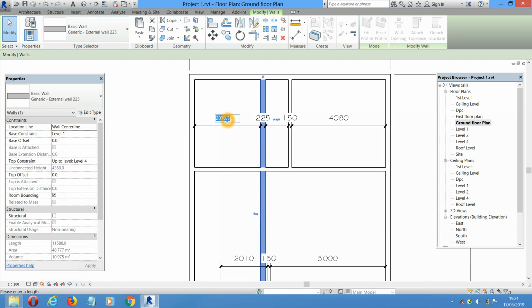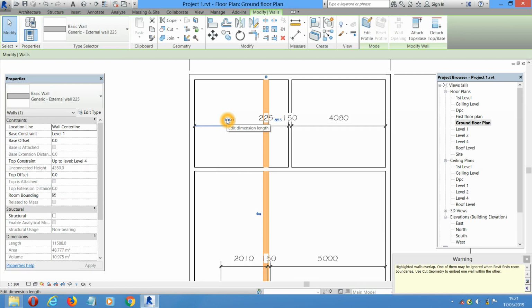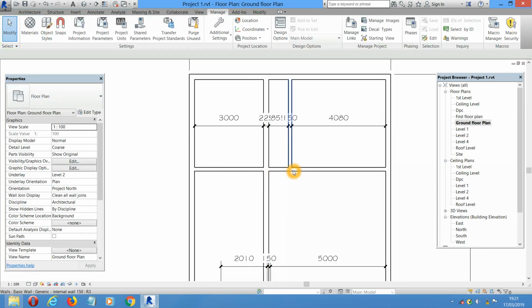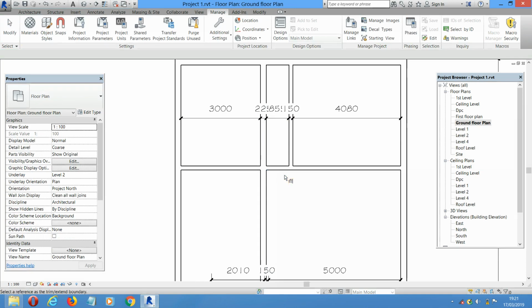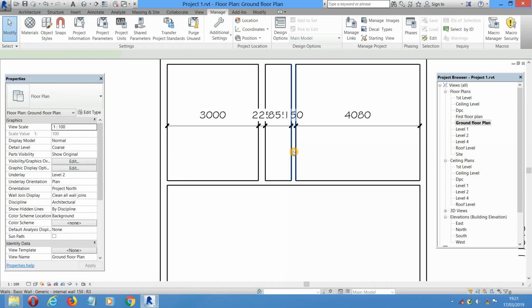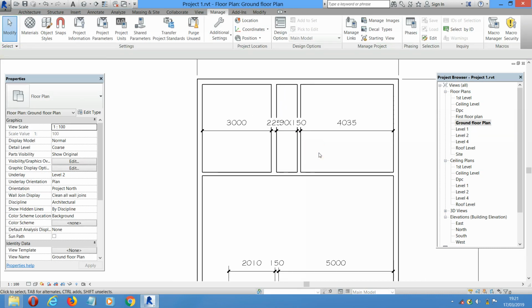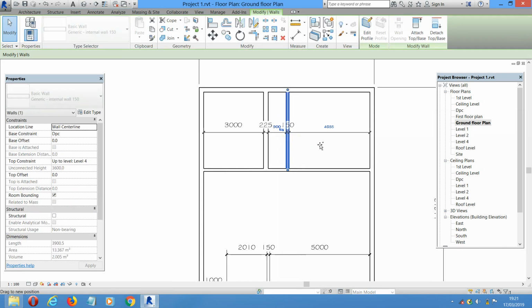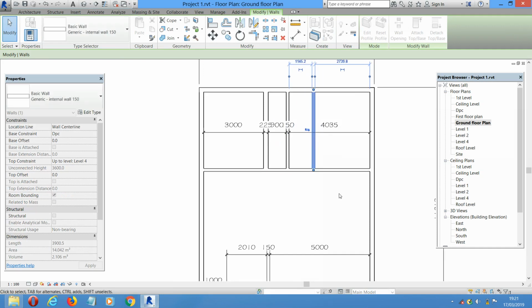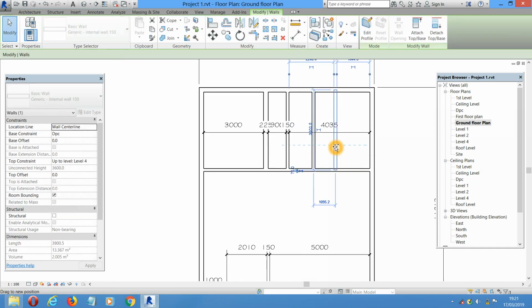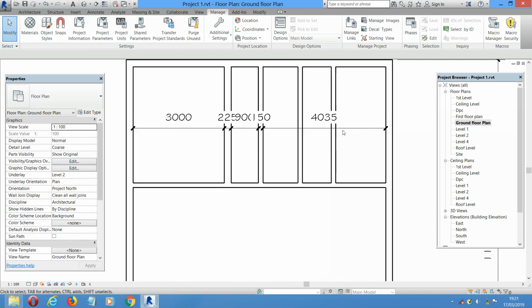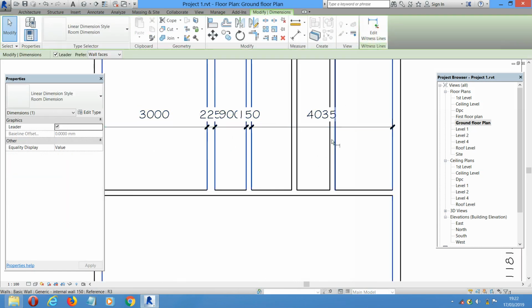So this guest room is going to be 3 meters. Hit OK. Then I'm going to trim that wall. EX is my shortcut for extend. Then this is going to be his own toilet. The width is going to be 900 mm. Then here we are going to have a store and toilet for BQ.